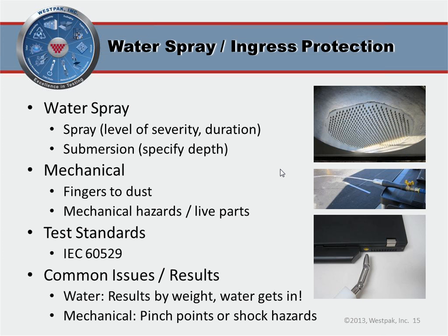Going to more severe, you get to water spray, like imagine a shower head, and then you get a water jet. That's what we see in the middle picture. And then we go all the way to submersion and then a deep submersion. So depending on your product class, what level of water spray is it likely to see in the field, you tested that. With the laptop, a brief light sprinkle is probably a fair thing to do, but anything beyond that would be extreme.